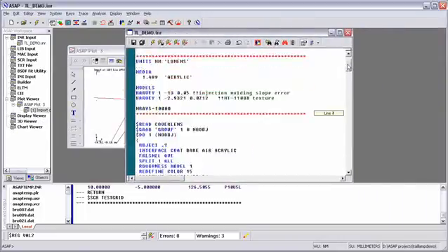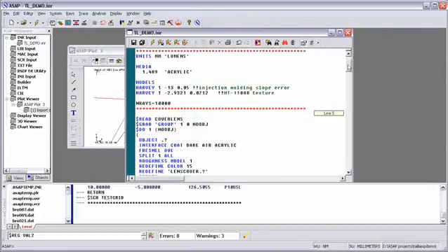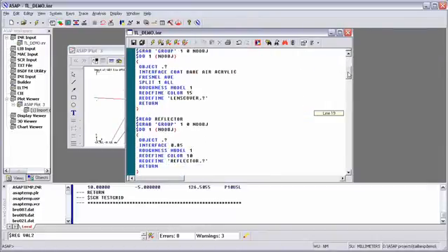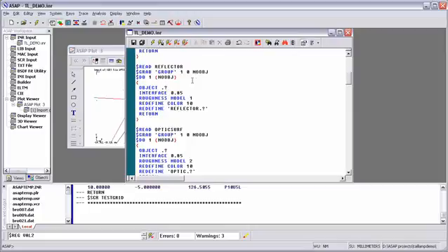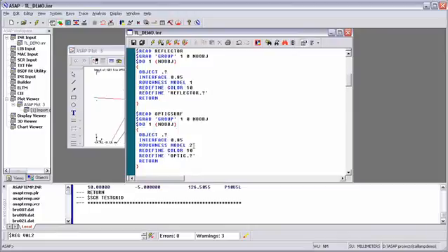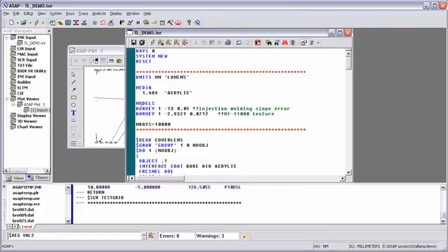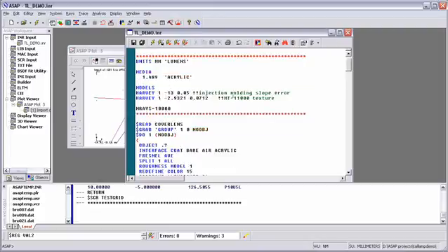I mentioned up front that I didn't do the material assignment to the geometry with the IGES translator to allow me to change the parameters of the design quicker. And one of the things that I've set up in this particular file is we have roughness models that simulate different surface finishes, one of them being a simple model for just simulating injection molding parts, because they're not going to be perfect, so it simulates a modest amount of slope error.